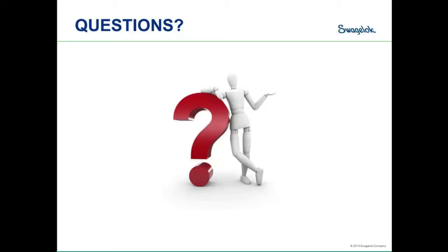No. So that is a great question. We certainly must have some experts on the call here, because that is one that we see all the time. So permeability, there's a lot of variability that comes into that. To give you some examples, if we had a hose that was 2 feet long, and then another hose, same materials, that was 50 feet long, put into the same application, so nitrogen or whatever it be, the 50-foot hose is going to show results of a much higher rate of permeability, even particularly over a period of time. That's because of the exposed amount of hose.